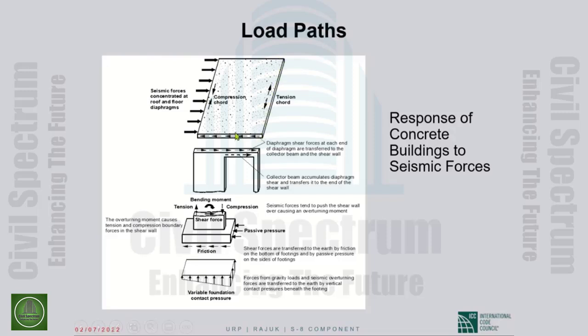And then along edges parallel to the inertia forces, we have shear developing. Those shear forces will be transferred to the supporting frames or shear walls, which will take them down to their foundations, and then the foundations will transfer the forces down to the soil underneath the structure, where all loads ultimately belong.